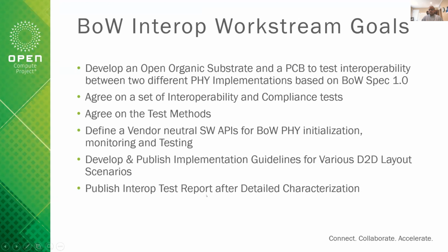We are also developing guidelines for die-to-die layouts. For instance, some layouts are very straightforward, connecting the two dies in a simple fashion, but there are also a lot of other complex interconnect structures that one could encounter in an actual design. So we're identifying these different cases and analyzing the performance. We'll also publish the results as we progress, along with the detailed interop test reports.